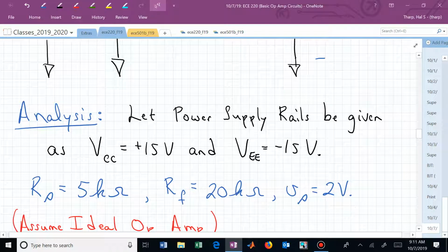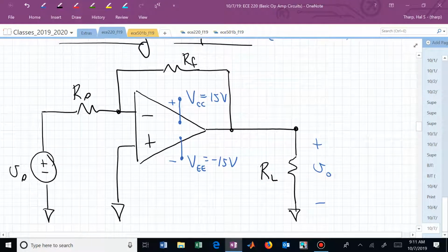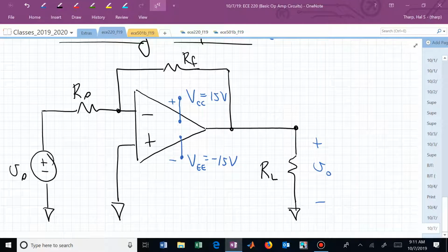If that's the case, how did we start saying that we would approach the analysis of such an op-amp circuit? What's the very first step that we need to make as we're examining the analysis of this circuit? What are we looking for? Do you remember? What's the key? Feedback. We need to see, is there feedback from the output pin to the inverting pin of our op-amp? Do we have negative feedback? And in this case, what's the answer?